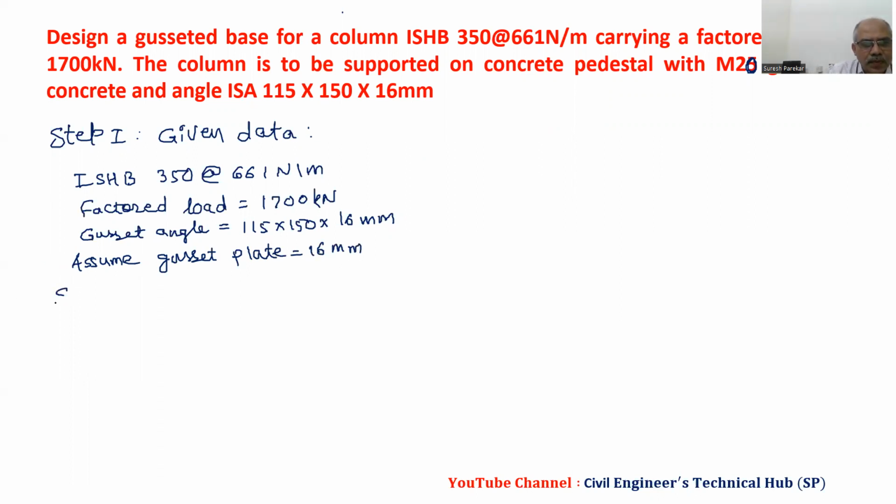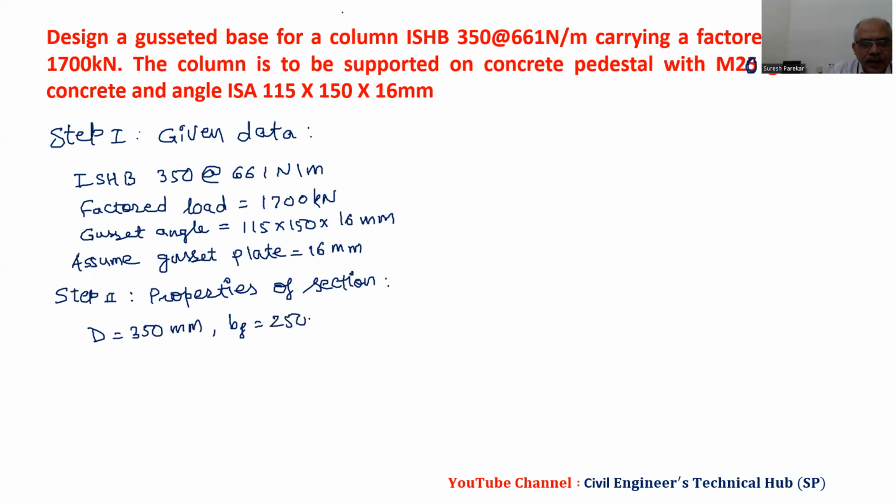Now we have step 2, properties of section. We have given D 350 millimeters, BF 250 millimeters, TF 11.6 millimeters, TW 8.3 millimeters.